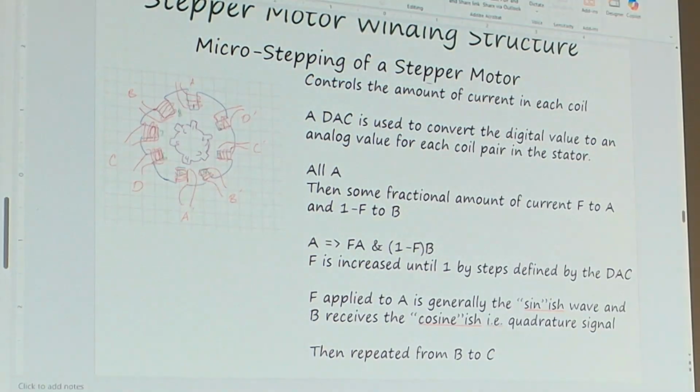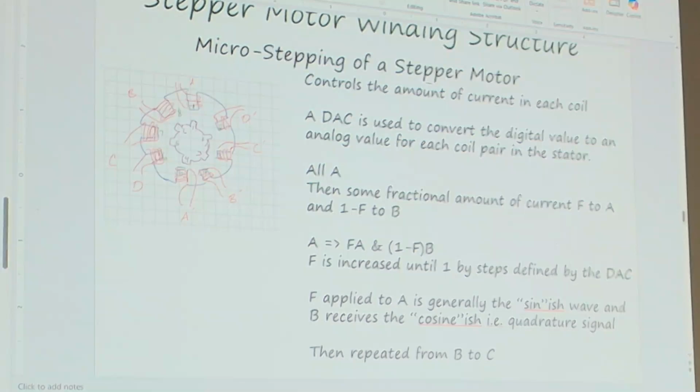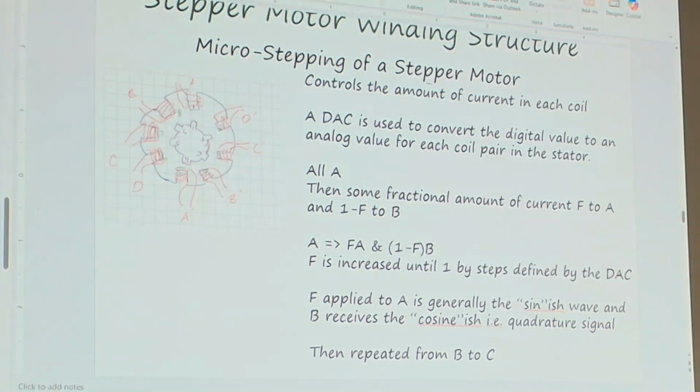If we advance it too fast, and our motor can't keep up, what happens? We skip a step. Here's the thing. You can say, I'm going to give it 10 pulses at a certain rate, and therefore it's moved 10 steps. But if it misses a step, how do you know? You don't, right? Or maybe it's got a load and it can't extend that load, but it's turning anyway. It's trying to turn anyways. I.e., your printer when it didn't hit that home switch, right? And it goes, now you said you got to rehome it.